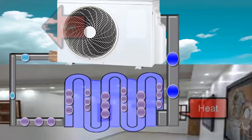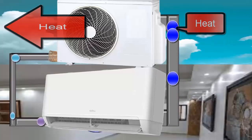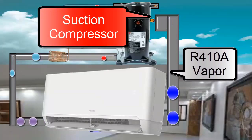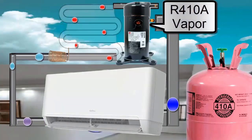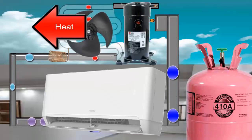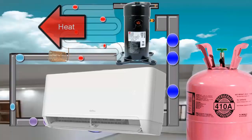To achieve the operating cycle, the compressor suctions the R410A gas in a vapor state and takes it to the outdoor unit, condenser. In the condenser unit, the R410A releases heat into the environment. To improve this process, the compressor increases the pressure of the R410A. Due to the high pressure, as the R410A releases heat, it changes from a vapor state to a liquid state.